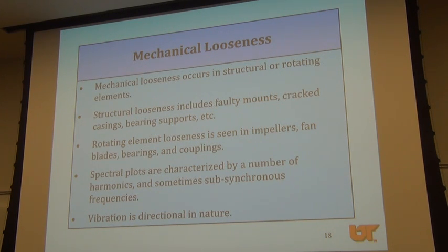Mechanical looseness is caused by, it could be either coming from the way you bolt something to the foundation, or maybe there is a loose pulley, loose gear, things like that, loose belt. So these things can cause looseness in the system, not properly tightened. That would cause vibration.